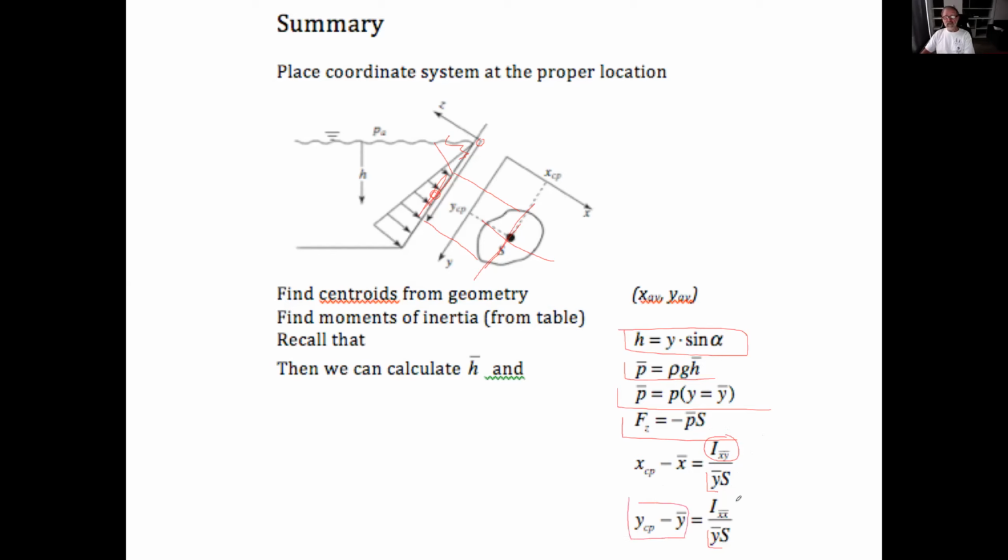So the same table, you find out what is the area and where is the centroid, you find out what is the moment of inertia. You know what is the area, y average, you just calculated with this formula. And that's very straightforward, very, very simple. Any questions up to this point? I think I can come back with examples which will clarify, but I want to make sure that the process is very, very simple. This is all we're going to do, okay? Because this was all the footwork to develop the simple approach that can help us to solve practical problems.